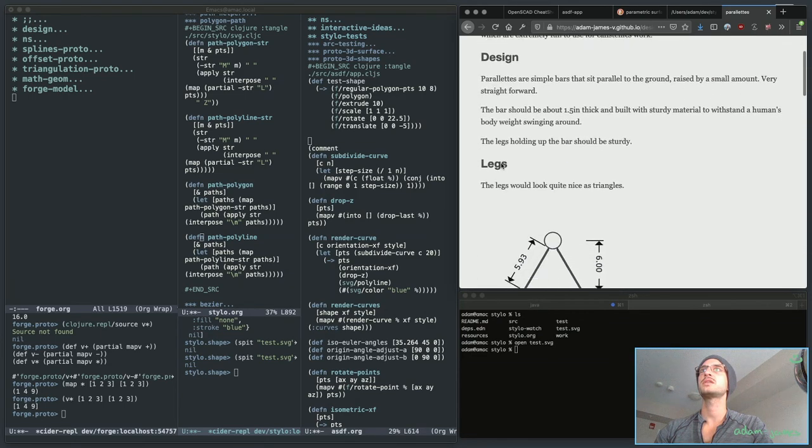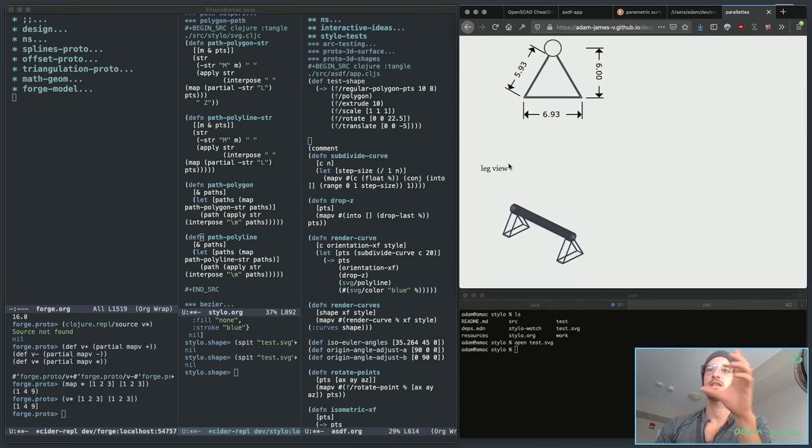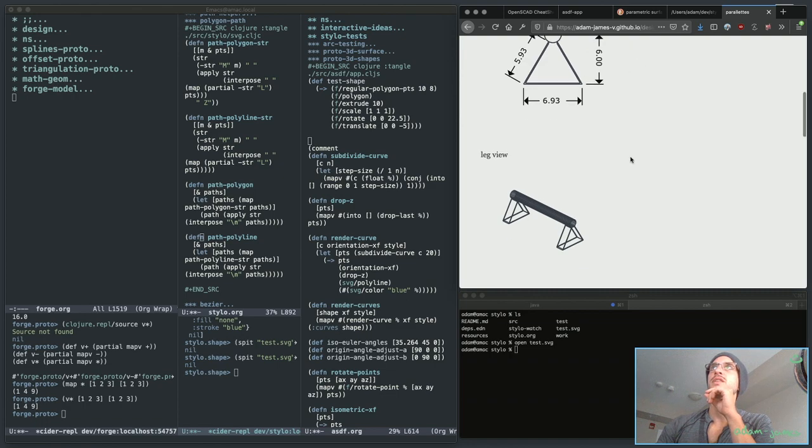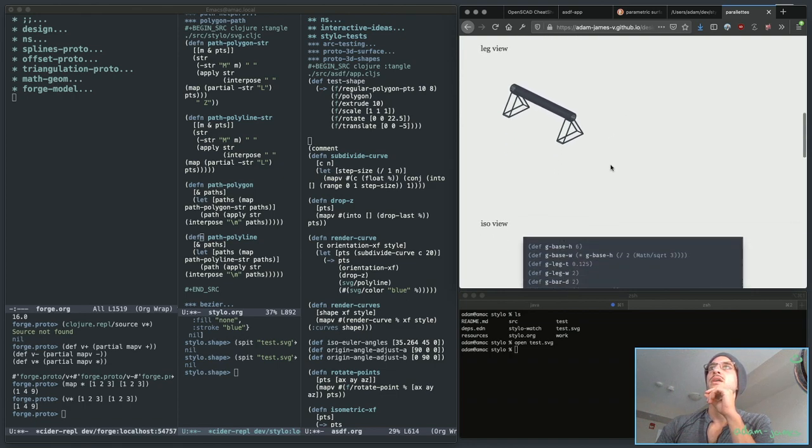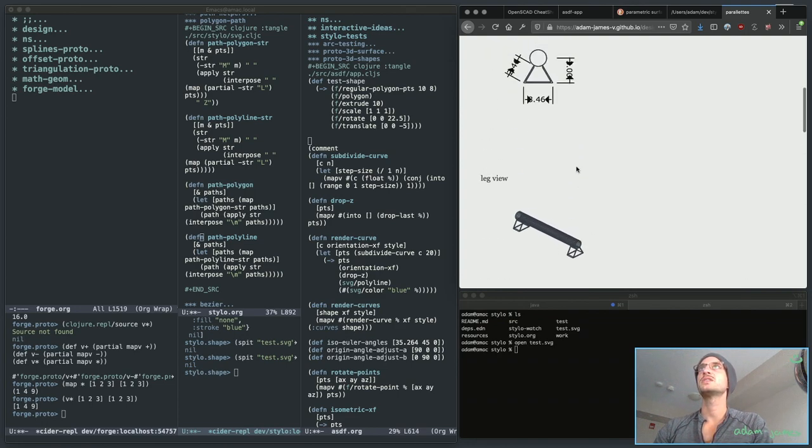So in theory you can have a rendered view with some critical dimensions on there. And if I change this base height to 3, it changes the shape of this, but it also changes the dimensions here, so theoretically, the drawing is now different.